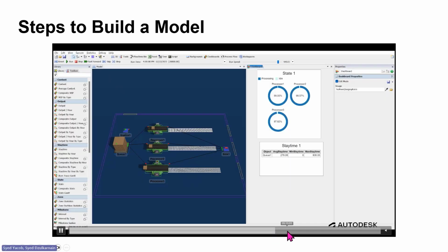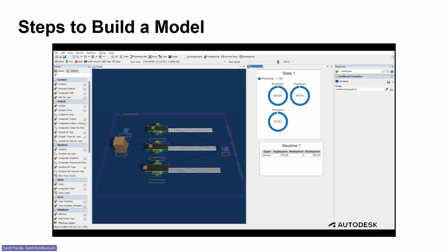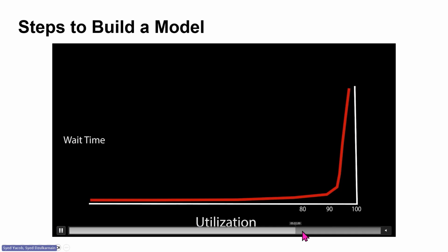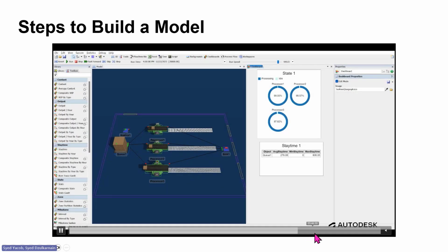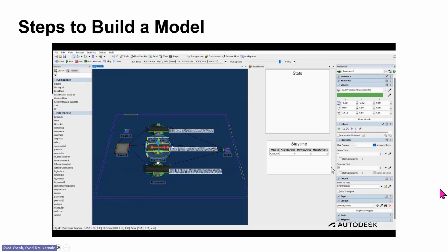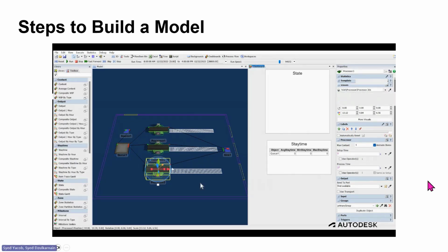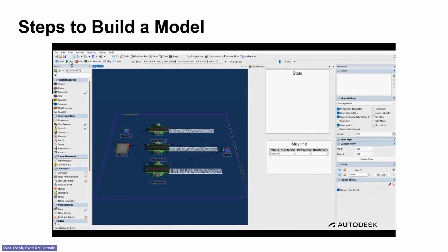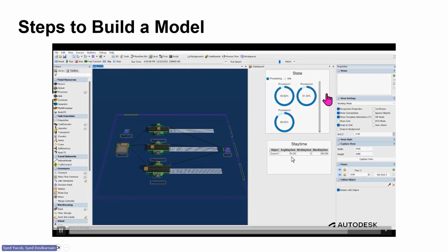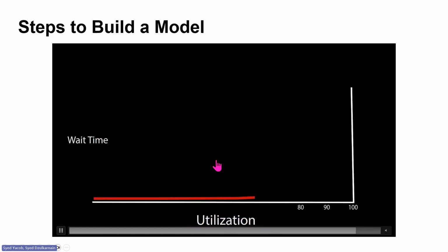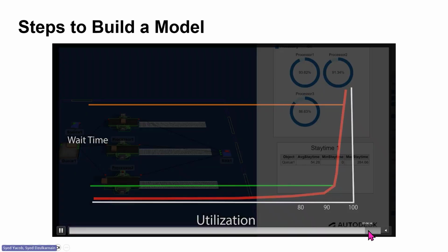And so let's say we change something. Maybe we add some bottleneck or some goals per hour, how much we need, to see how the process looks. After we specify the process time, change the details, we can see we get a different result. Run this simulation, and you can see our processors now run almost optimized: 93%, 91%, and 86%. Probably at processor 3 we can fully utilize. Why is it different? Probably because of how far it is from the raw material storage. So that's probably the cause of it.